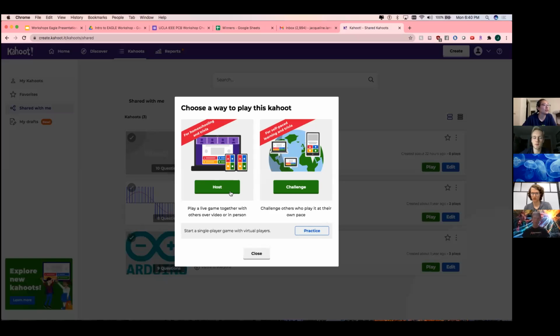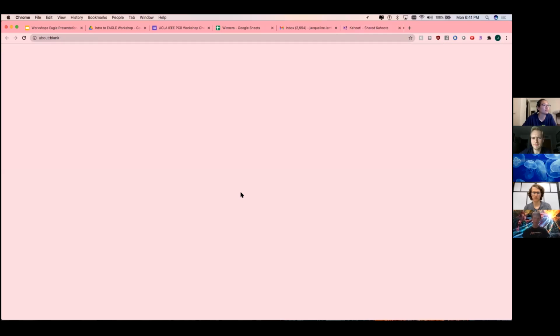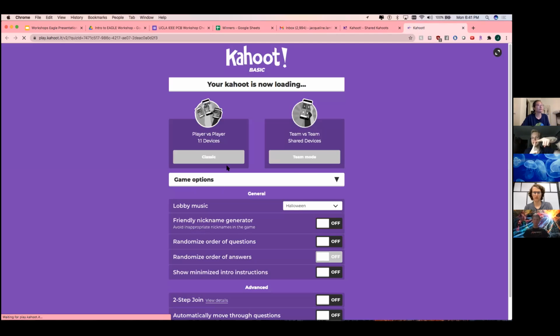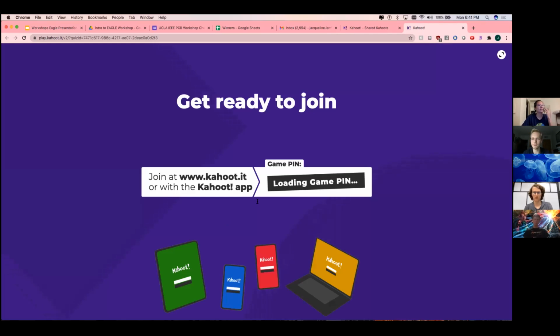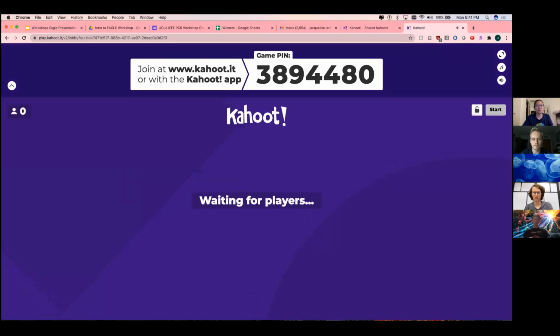All right, Grace, in answer to your question about right angle traces, which is a very good one, there's some debate as to whether or not it's actually a myth, but they say it can disrupt the integrity, especially of an analog signal, that rounding that bend instead of going more smoothly around it. So some people say it's not real. Some other people say it is real. So it's just best to be on the safe side for that.